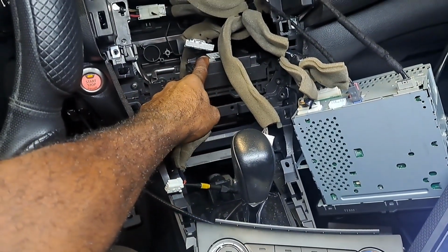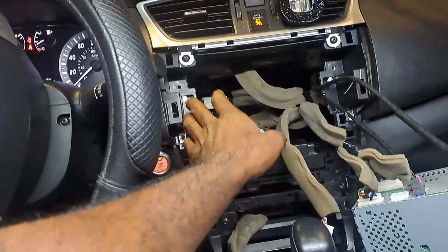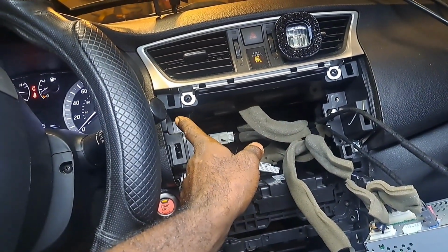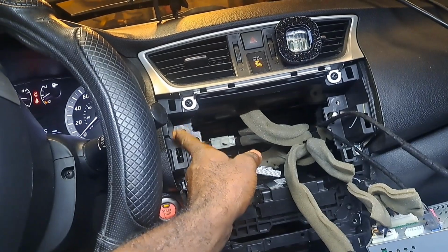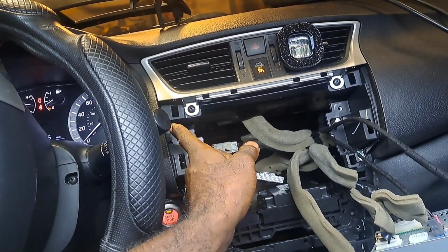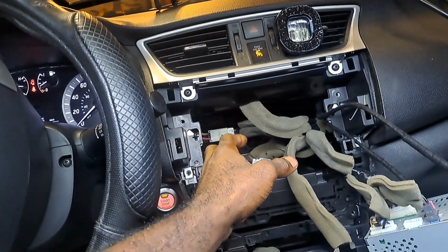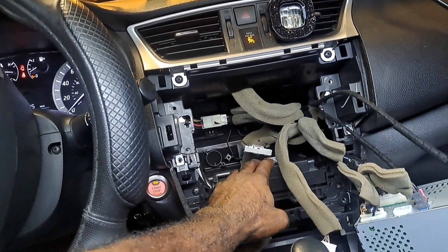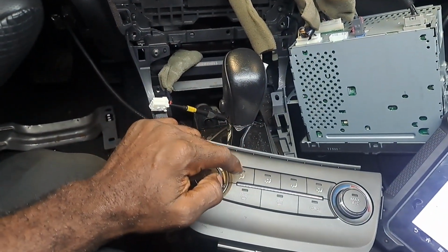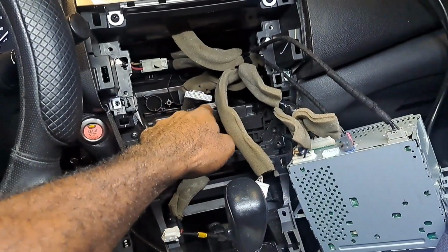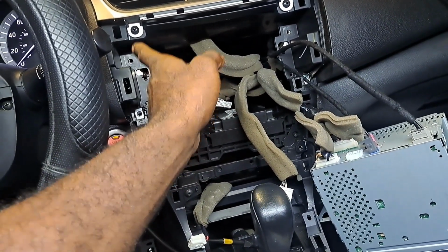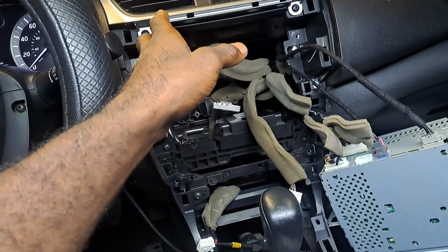The command gets sent to the AC amplifier through the control area network, and then the pulse width modulated signal is sent to the blower resistor, and the duty cycle is sent out to the blower motor to operate depending on the duty cycle commanded. So this works from a control area network from here to there. The duty cycle is sent from there to the blower resistor, and it works off whatever command state is given.